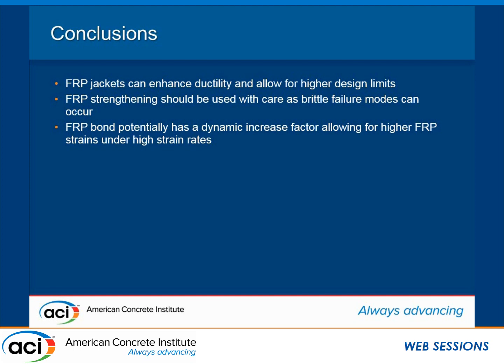Now, if heat is an issue, of course, you're going to have to worry about protecting your FRP. But I would probably argue that the heat would take a bit more time to affect the FRP and the resin and the bond than the actual action of the blast and the response of the member. Because here we're looking at several milliseconds rather than complete seconds that even a very high temperature heat would take to start to soften this material.